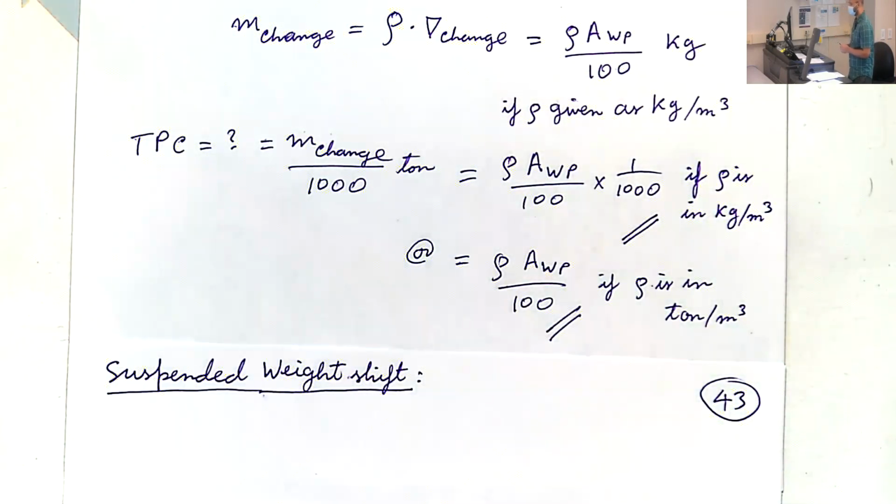When you do these things, you change the static stability of the ship significantly. The reason is, first thing, you are shifting mass. So again, these angle changes will happen, and you need to make sure that it doesn't exceed your requirements.